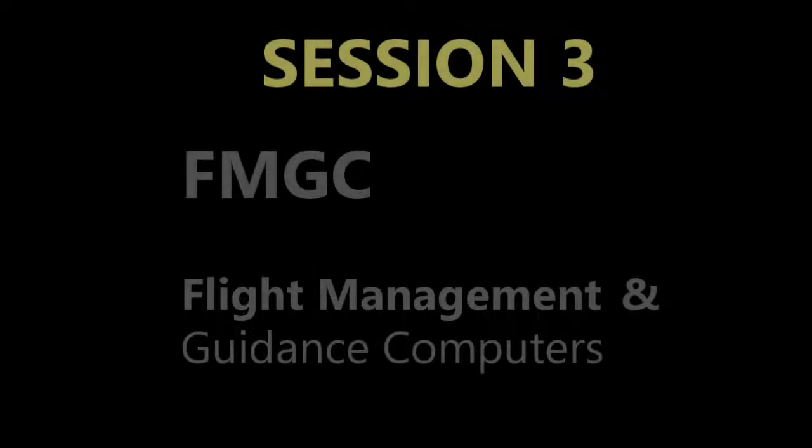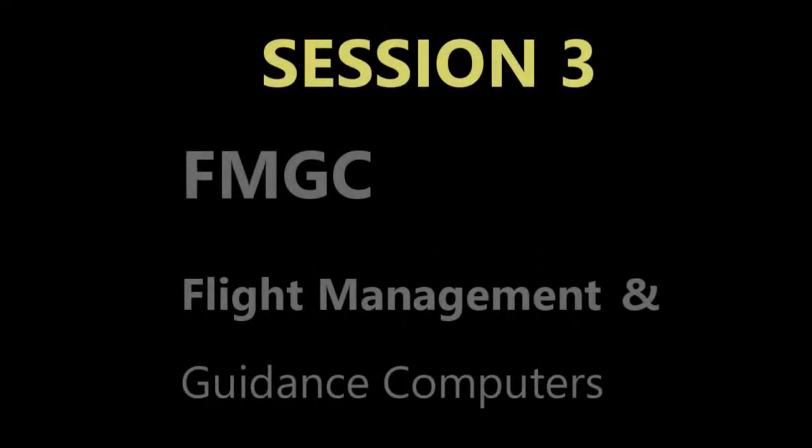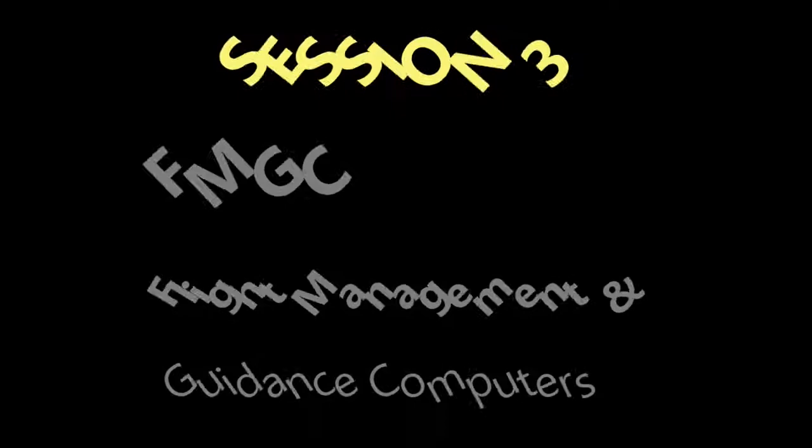Okay, so let's start with the push buttons. Like I just mentioned, you've got 2, AP 1 and 2. So those are your 2 autopilot push buttons. And you can engage these after liftoff. Okay, you have to reach about 5 or so seconds after liftoff. And those can be put into play by the pilot. So those get engaged.